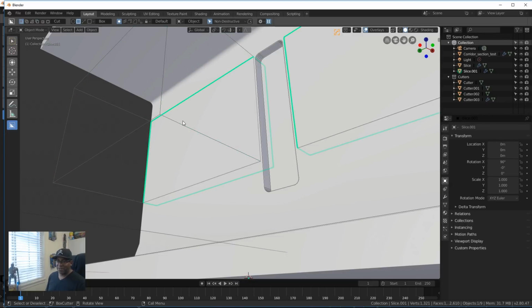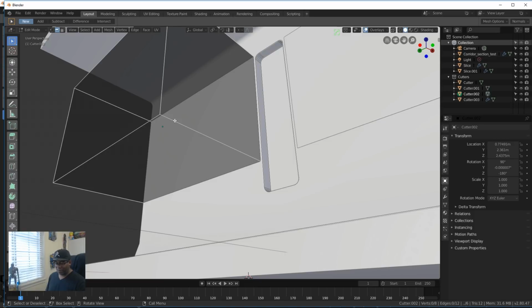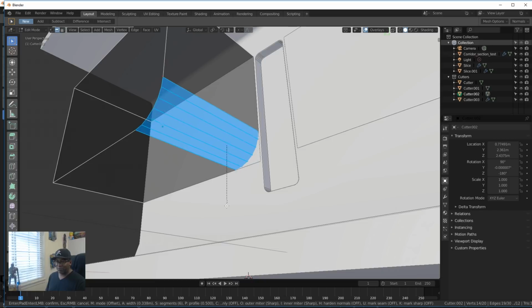So if I take it from the edges and I actually tab into this shape and edit it, like I can undo it all, or unselect it all actually, sorry, grab the vert, actually put maybe like a bevel on here or something like that.